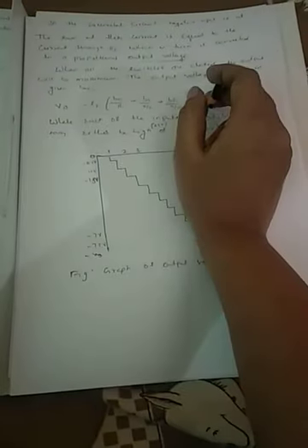So depending on the switches from B0 to B3, either closed or open, binary weighted current will be set up in the input resistors. So this part will be acting as a summing amplifier when more than 2 switches are closed, and we can calculate the output voltage as we have calculated now. Now the sum of the currents through the resistors will be the same as the current through RF, which is converted to proportional output voltage.